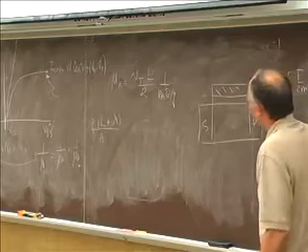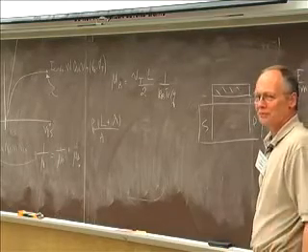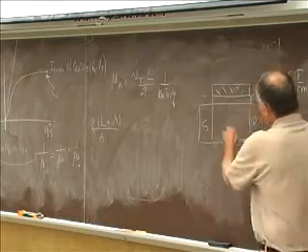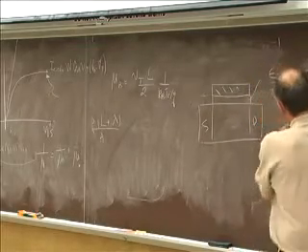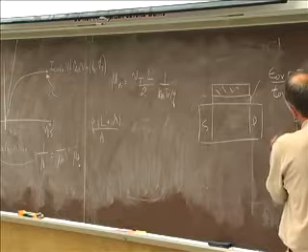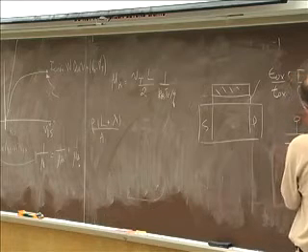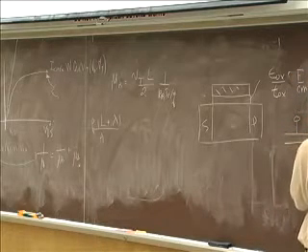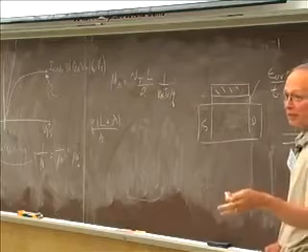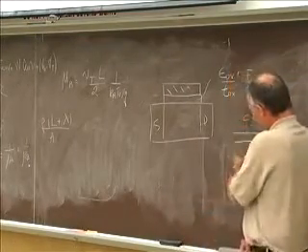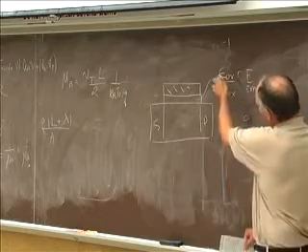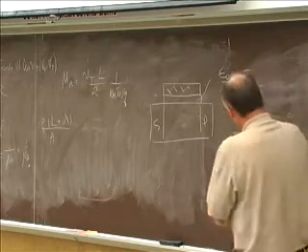Okay. But that's not quite true, because the semiconductor channel itself also has some capacitance. So the actual capacitance is this insulator capacitance, or if you've replaced SiO2 with something else, like Intel has, then it's some other insulator capacitance with a different dielectric constant.